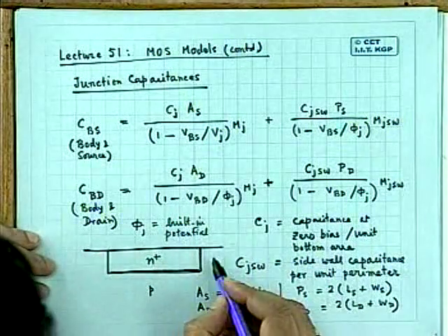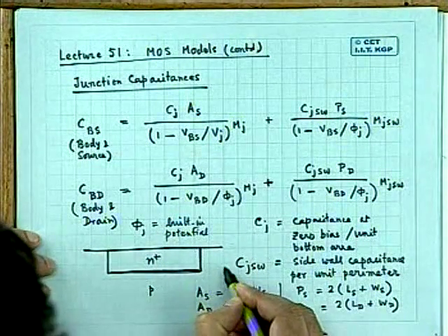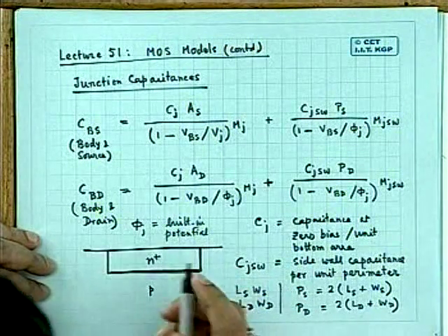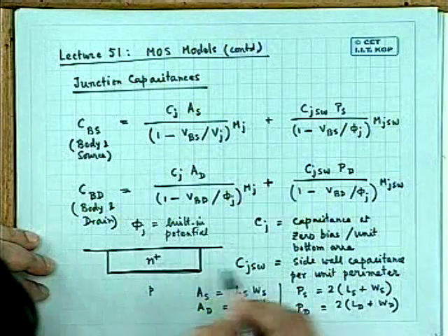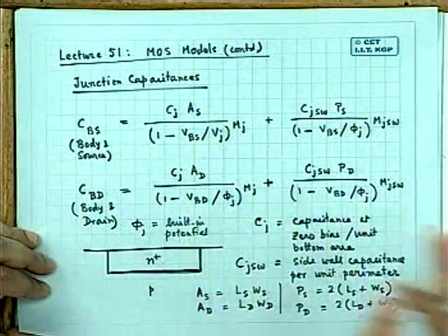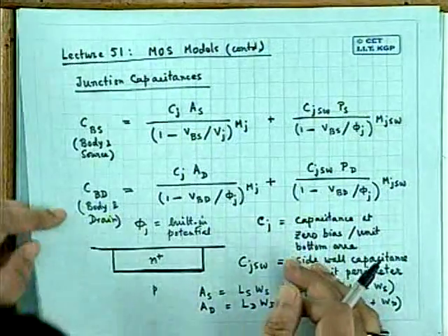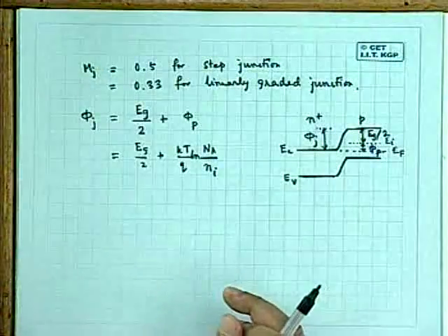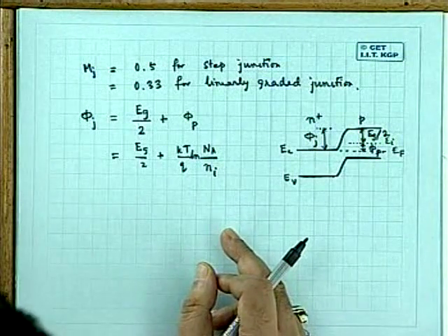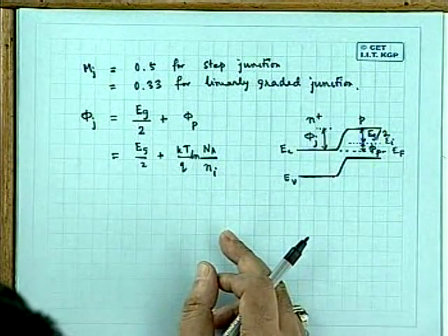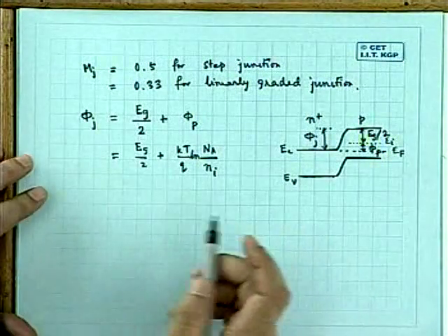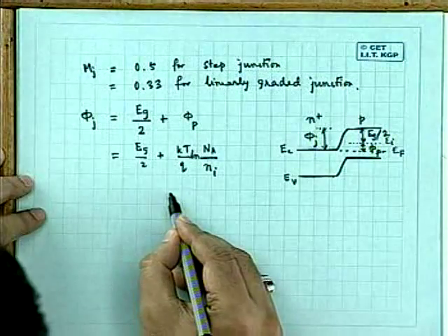In modern technology, what we do is replace it by an oxide. Then it is called oxide isolation. You remember, that is done at the left of the source and at the right of the drain, to improve the isolation between the components. There, of course, these equations have to be suitably modified. As I was indicating, but let me just slightly discuss it.